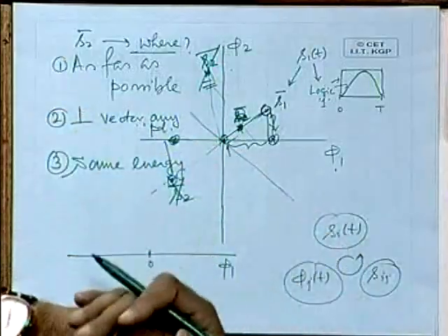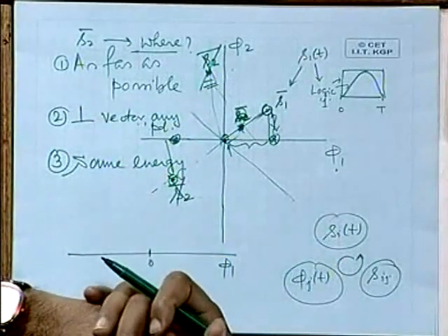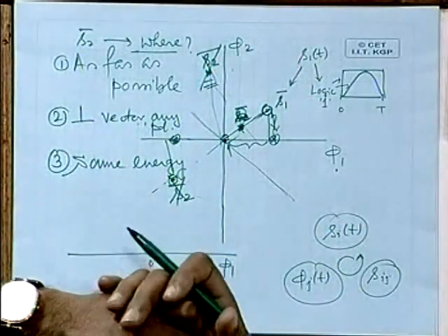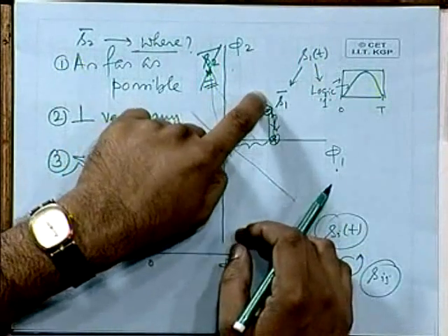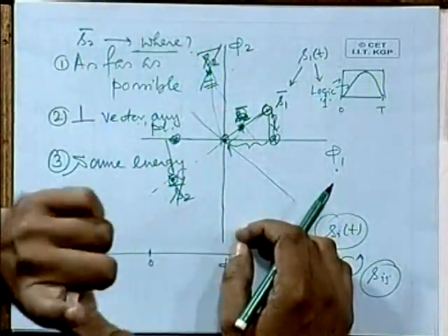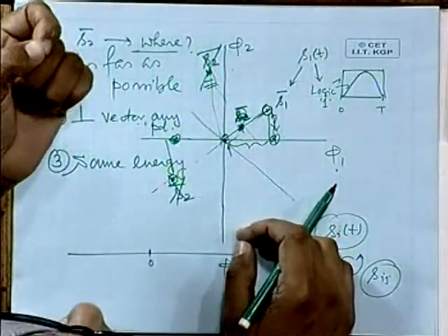Okay, tell me if I would have chosen S2 here at the origin, anything wrong? Not wrong. So, what I am simply saying is that one signal I transmit with good energy, the other signal I transmit with 0 energy really, I do not transmit anything. In fact, we had this example some time back in some other context, really we said that it is an on off kind of modulation scheme, okay, isn't it? Yeah, right.